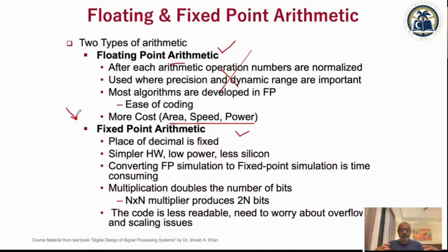So you can basically squeeze all your variables into fixed point format. Fixed point format means that you fix the decimal at one location. Let's say you choose 4 digits in the integer part and 12 digits in the fractional part. Once you fix it, it remains fixed for all the variables unless you change it yourself. So you have to move the decimal by yourself.